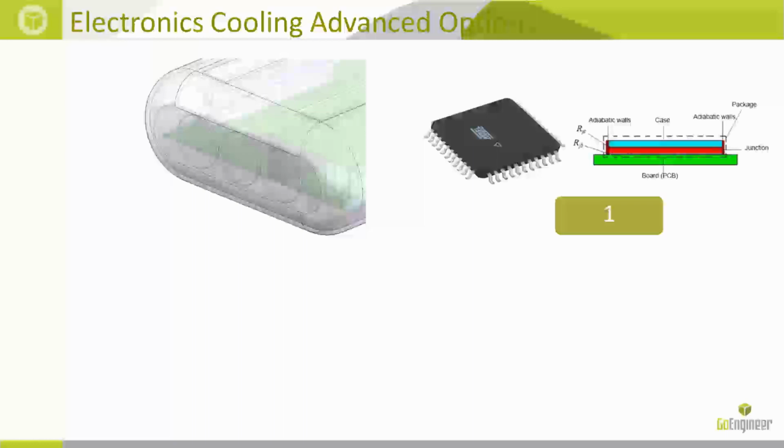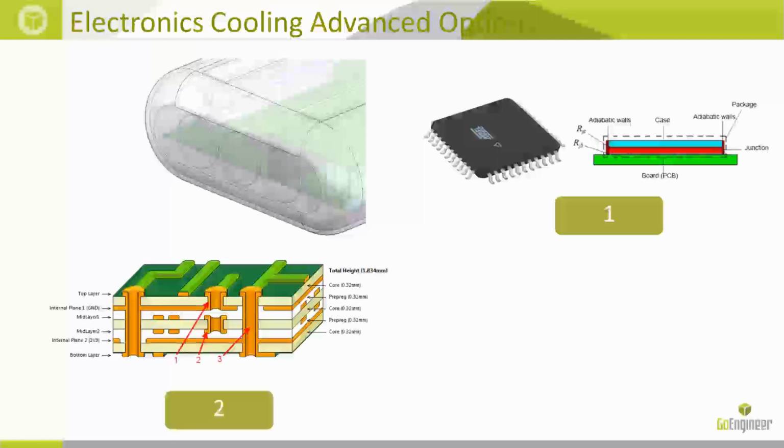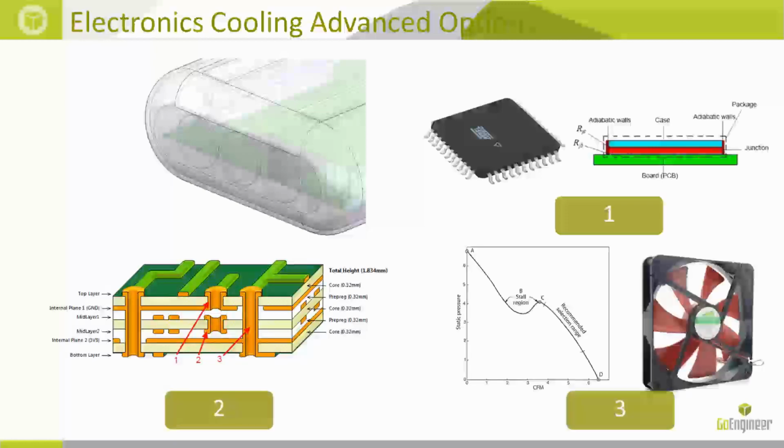We simplified them with just 2 rectangular extrusions, which I will be talking about in just a little bit. We also simplified the PCB generator, and lastly we looked at a simplified fan by just providing the inlet for it, and all the specifications of the fan were already part of the extended engineering database that we have inside Flow Simulation.